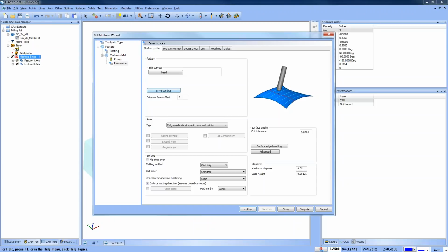If you have to do quote-unquote trickery, you can definitely get it done, but as your production level goes up, it will slow you down with trickery. Okay, so I do recommend looking at the software and the features and what best benefits you, and really understanding how those features work. And for ZLevel Finish, the advanced ZLevel Finish with the adaptive step-down is a really good feature. So if you don't have it, I would recommend considering it.